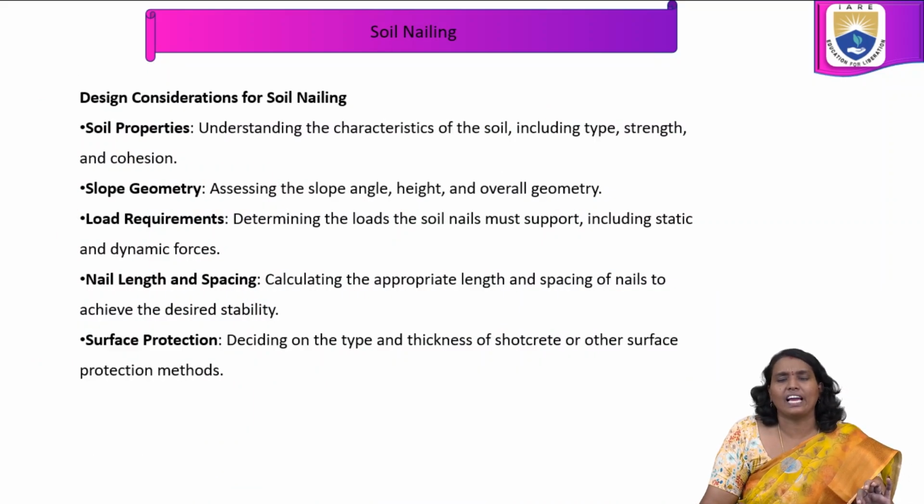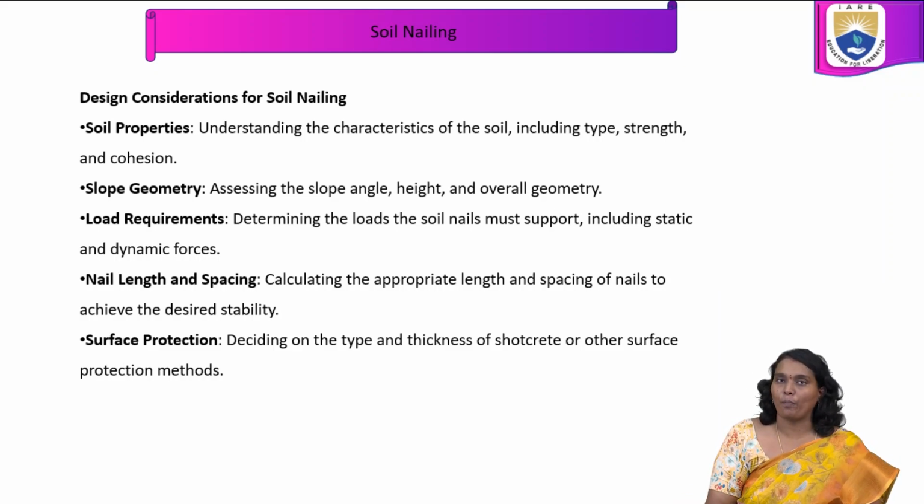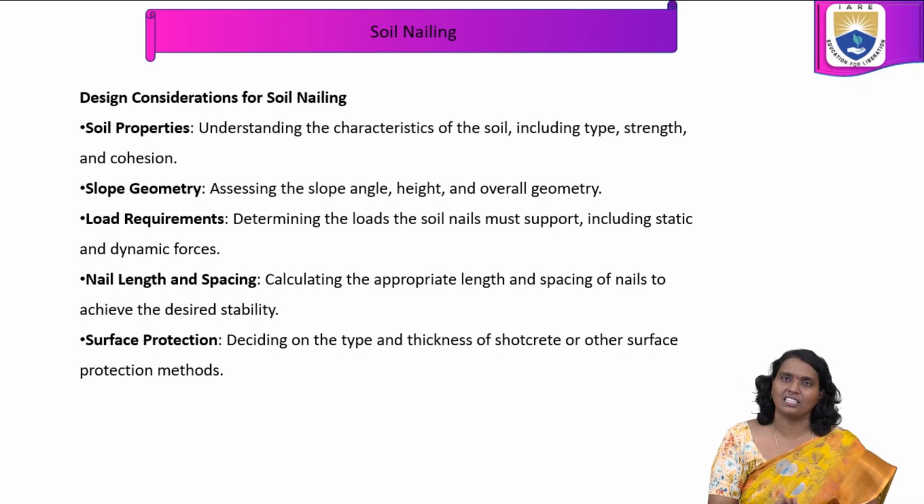What are the various design considerations for soil nailing? This depends upon the soil properties, slope geometry, load requirements, nail length and spacing, and surface protection. These are the major design considerations for soil nailing.